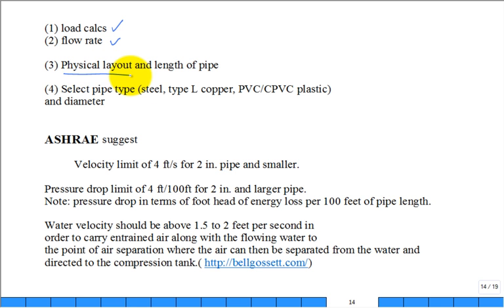You then lay out the pipe. You say, I'm going to have to turn here, turn there. I'm going to this building over here. I'm getting to the 3rd floor. You have to calculate all those lengths. Because it's a closed system, you can almost neglect the elevation. But if you really wanted to know the pressure in that pipe at that location, at that floor, you would need to know the elevation because it's always hydrostatic head. But the pipe takes it up, the pipe takes it down. In the net, it's not like splashing it up like an open system.